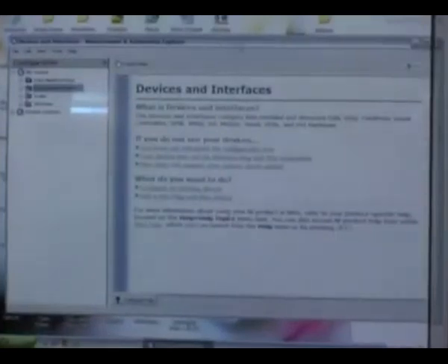This is the control program based on the LabVIEW platform. LabVIEW is software; the acronym stands for Laboratory Virtual Instrumentation Engineering Workbench. Here we have used a stepper motor card, the NI 7358, which has 8 axes, meaning we can control 8 motors. Here we are using 6 motors, and all those 6 motors are different types of stepper motors, all interfaced to this control card.